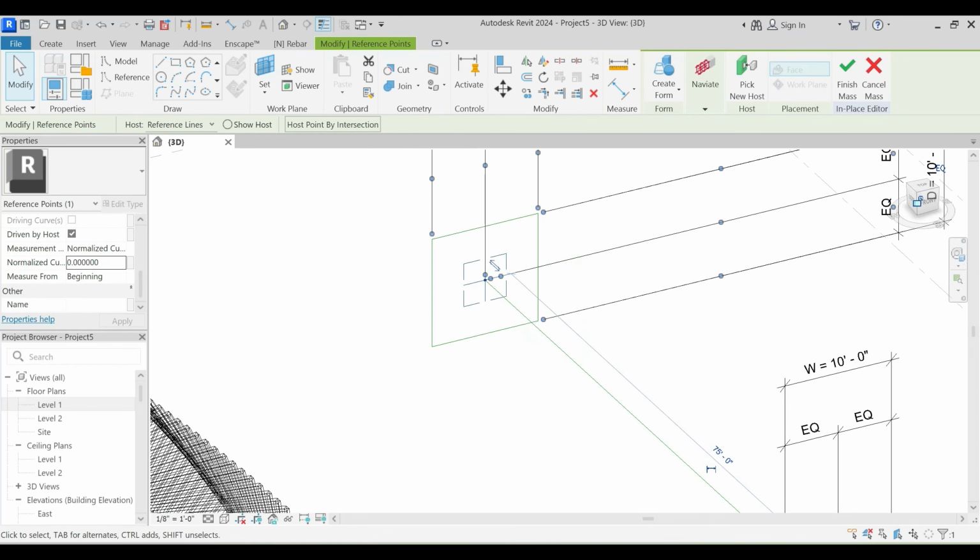So I will just select this particular divided surface and change this particular number to 25, grid rotation for this particular U grid to 30, and similarly for V grid I'll change this number to 25 again, and this to 60. That is because I have already tried this particular thing for that dimension. If you are dealing with a different dimension, then you have to try that particular thing. Okay. And you see that 1 and 2 modules within that particular this divided surface. Fine. So we need to do that for all the surfaces. I will just press tab and select that surface.